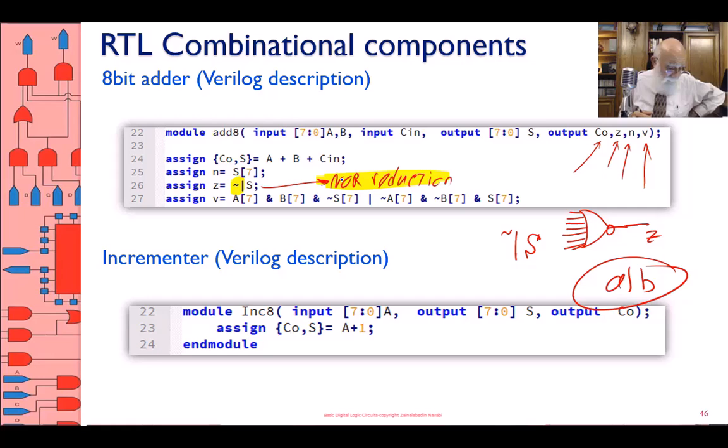And that's a different ORing than this ORing. See, this ORing has two operands on the two sides of it, and therefore the two are being ORed together. If what I'm ORing are vectors, then it will be bitwise ORing.